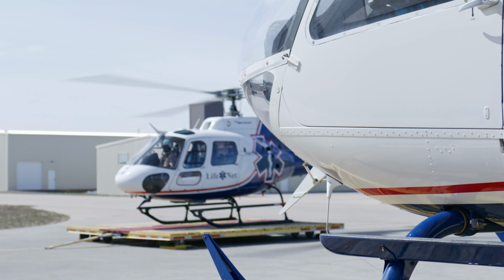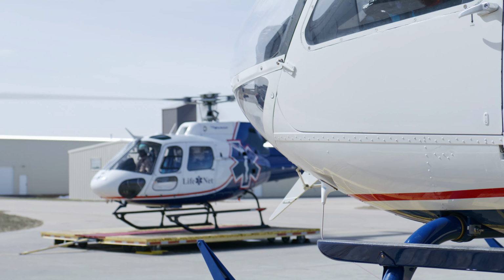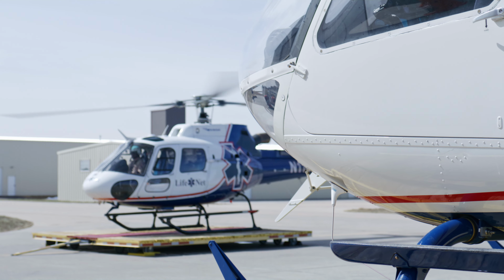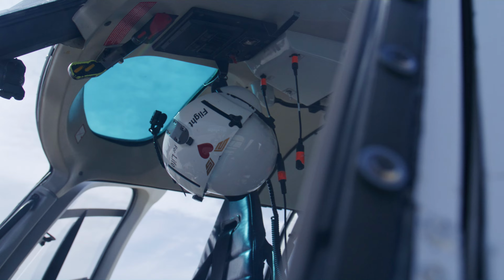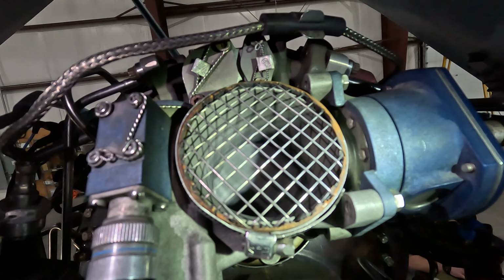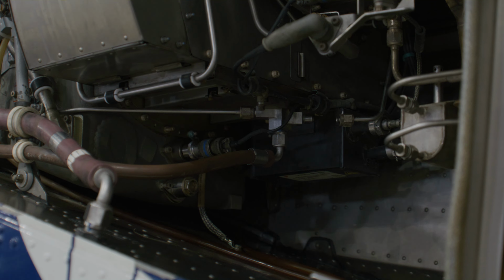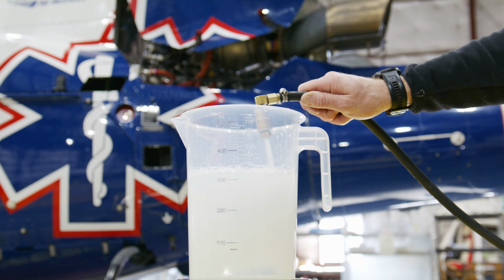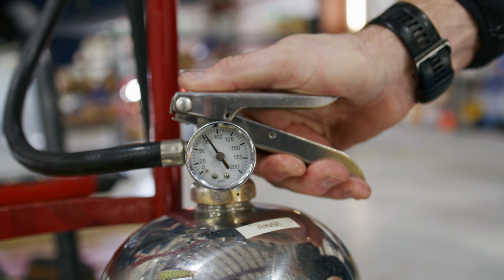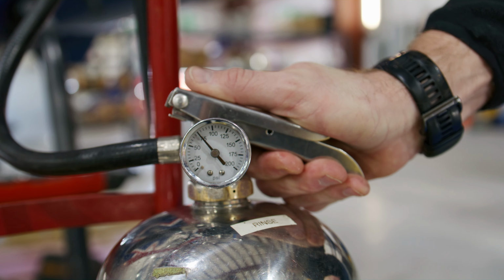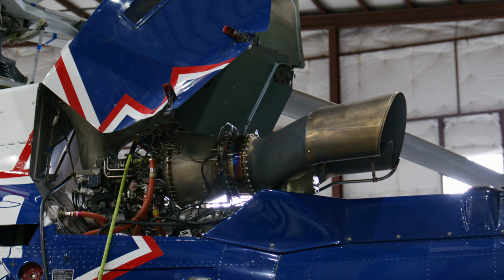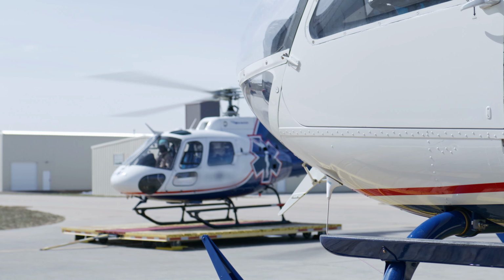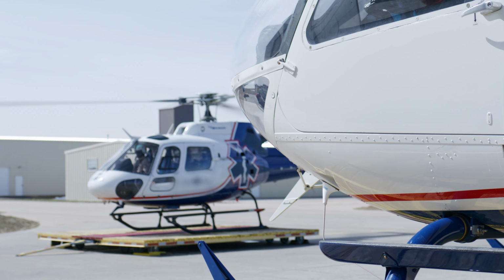Air path cleaning applies to every engine operated in any environment, and while every detail in this task is important, the key points are aircraft configuration, bleed valve closed, main injection drain line disconnected, water quality, precise cleaning chemical quantity and mixture ratio, do not guess, injection flow rate, verify your flow rate, soak time, rinsing quantity, and the drying run. Take the information presented and apply it going forward.